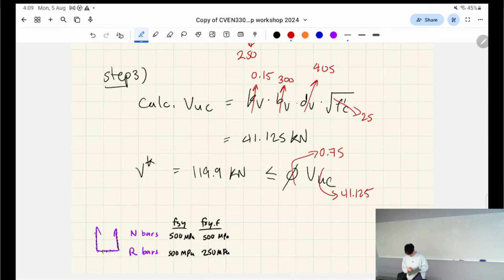And the answer is no. And this tends to be the case unless we have slabs. Slabs are able to take on much more strength because the width of a slab is 1,000 mm, right? We do a strip for a slab. That's way wider. Once we have a really large width, the concrete can start taking on a lot more of that shear action.